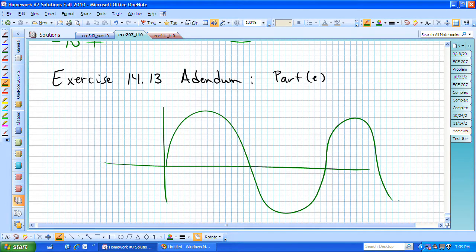That's not a very accurate sketch, but we started up and we went to 2.5, but now what we're going to end up with in the steady state is we will now be equally centered around a 0 level voltage, but now we are only going to be changing 2.5 volts per every half of a microsecond, which means if we're now equally distant positively and negatively, we have a 2.5 volt peak to peak.